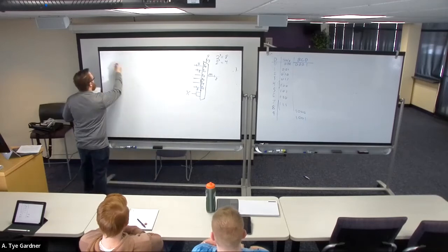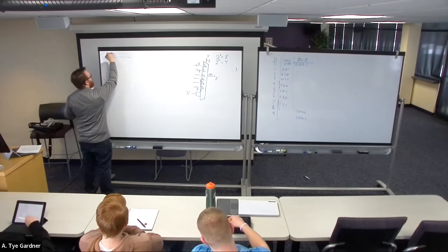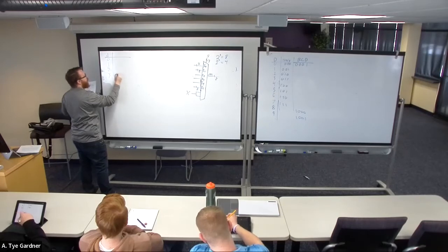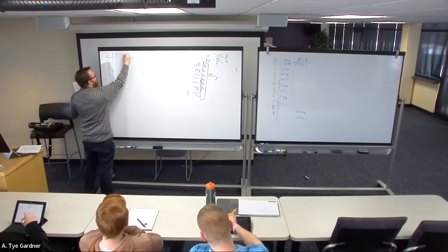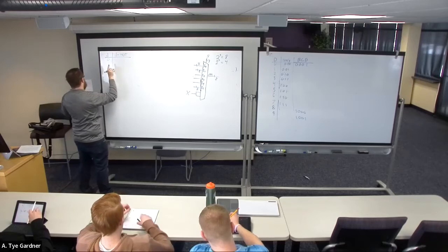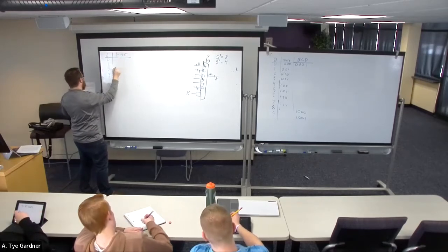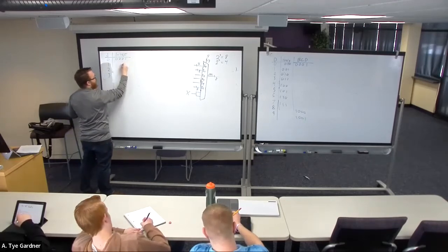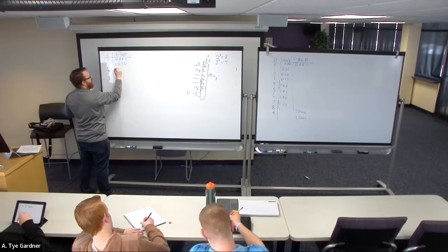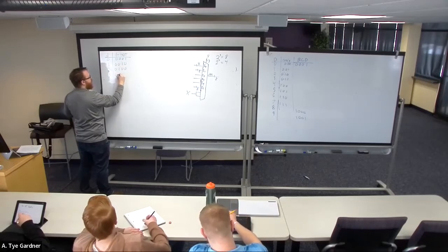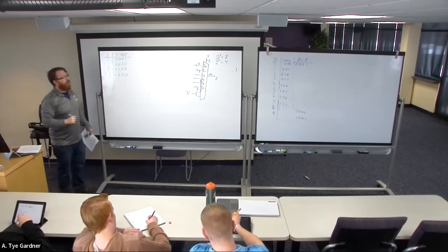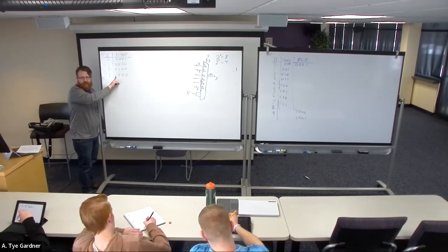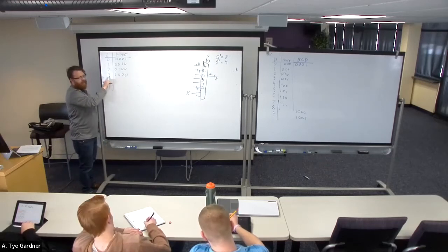Well, all one hot encoding is saying is that if I have the decimal number 0, 1, 2, 3, and I want the one hot, then my 0th option is, well, if I have 4 options, I actually need 4 bits. 0, 1, 2, 3. That's one hot encoding. It's just saying whatever my selection is, that's where the 1 is. Right? So the 3rd digit is a 1, that means I got a 3.